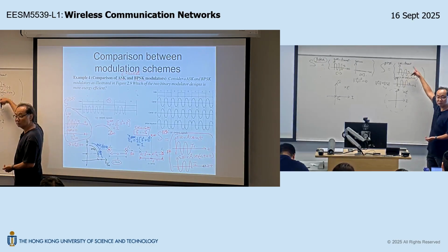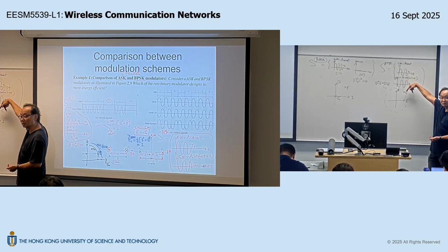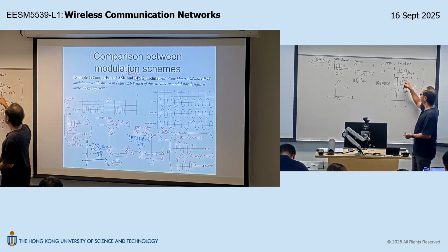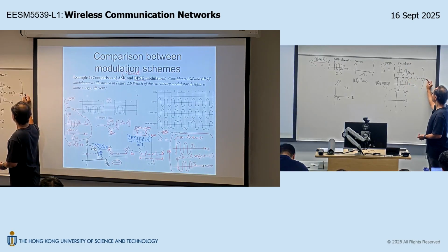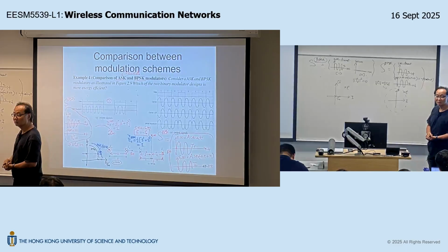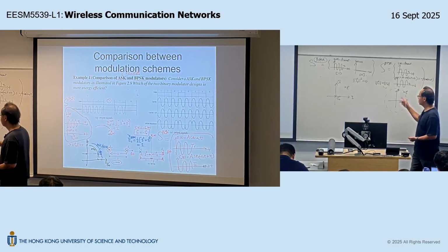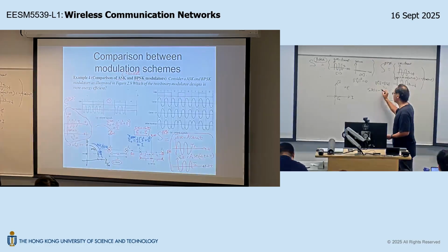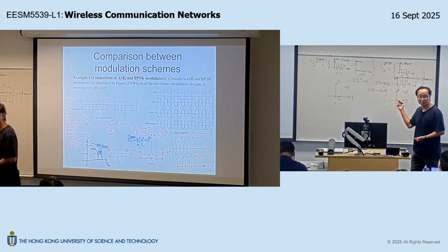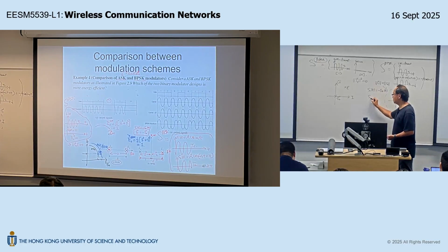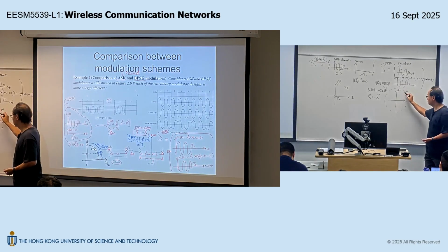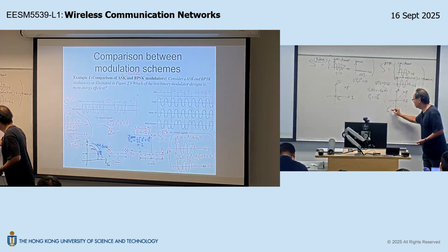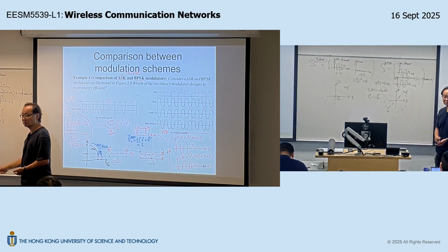You look at this waveform. It's not just equal energy, right? What can we say? Cosine omega ct plus pi equals to what? Equals to negative cosine omega ct, right? So that means S1(t) equals negative S2(t). Can we see that? So if we convert that to vectors, that means S1 is equal to negative S2. So this gives you a constraint. If S1 is here, S2 can only be here, equidistant and directly opposite.